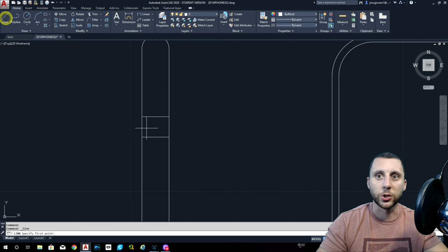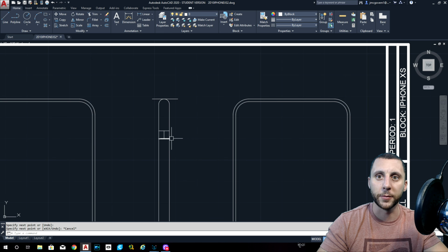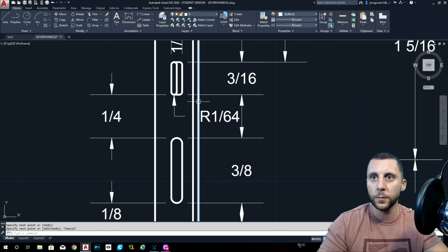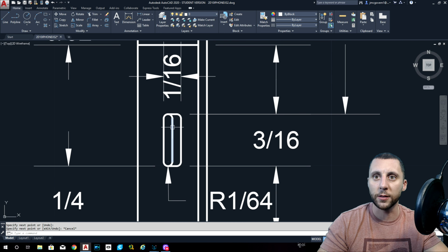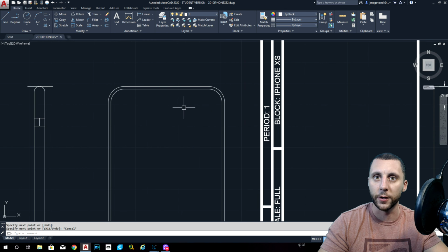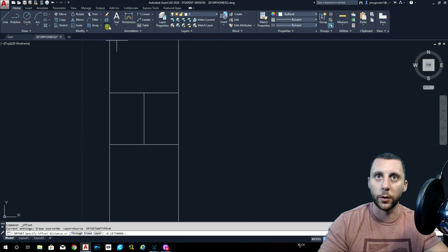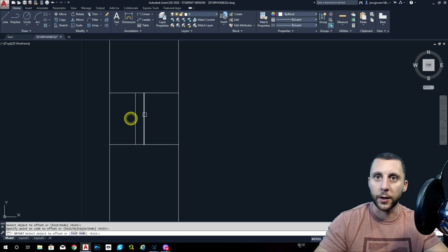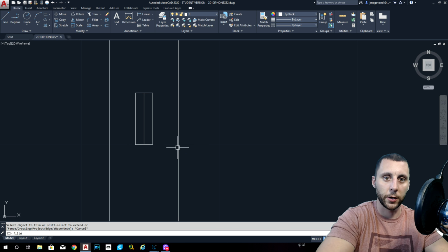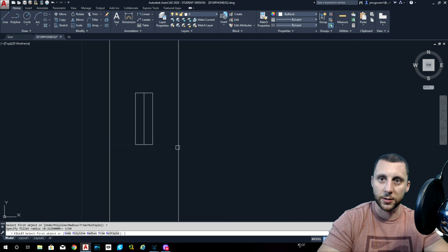All right, so you trim those, you put a line down the middle of them. Now we've got the center of it. Down the middle is this line right here. The entire width is 1/16. Half of that is 1/32. We go 1/32 left, 1/32 right, and then we have radius 1/64 for the fillets. So here we go, 1/32 left, 1/32 right, trim, whoops, fillet, radius 1/64.